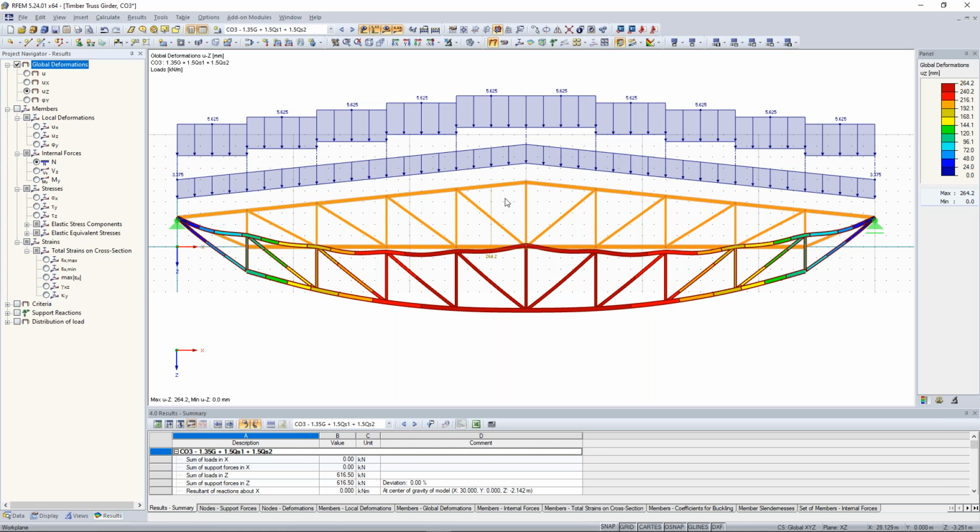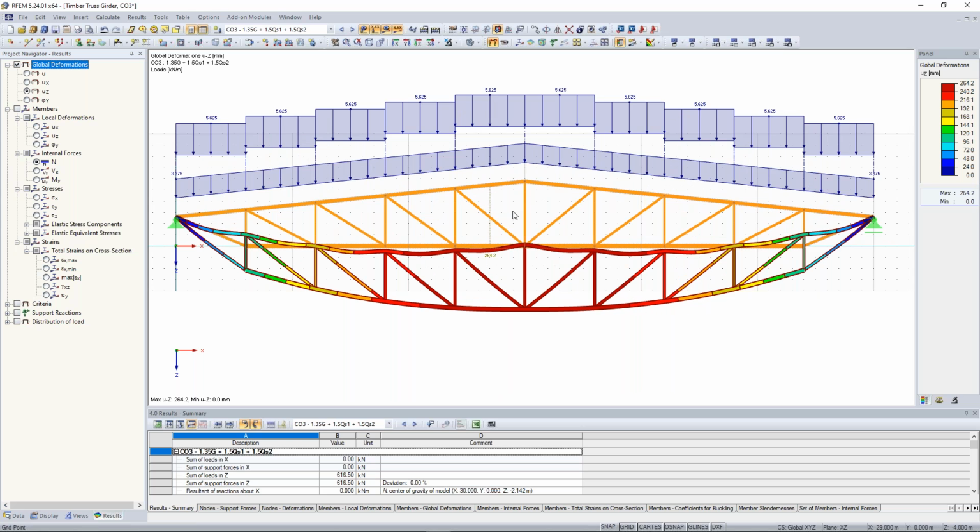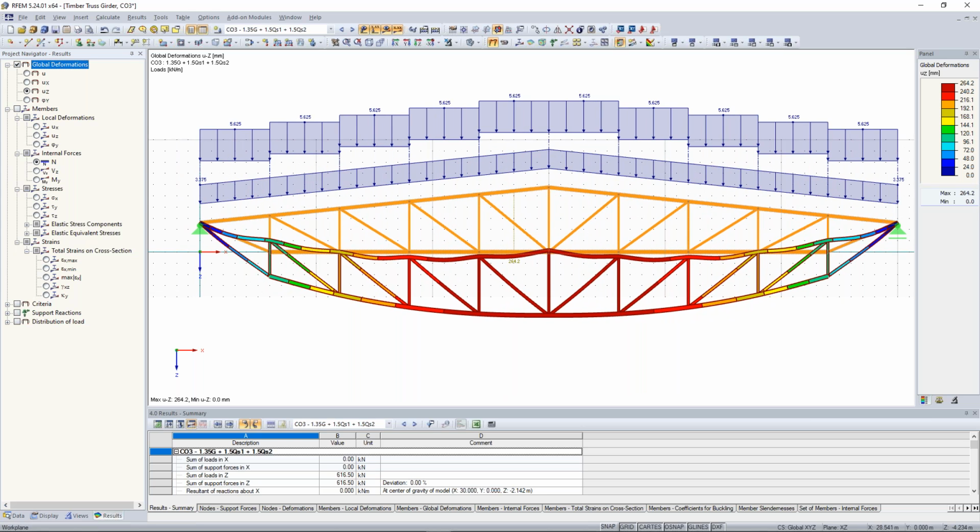Maybe you can optimize your construction for the verticals and the diagonals, because here you will get more tension forces. So you can say, okay, the first 2 rows of this diagonal can be a different cross section and put them then into the design.